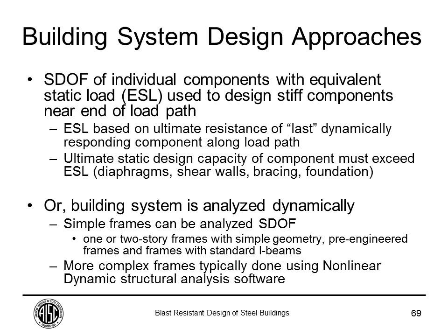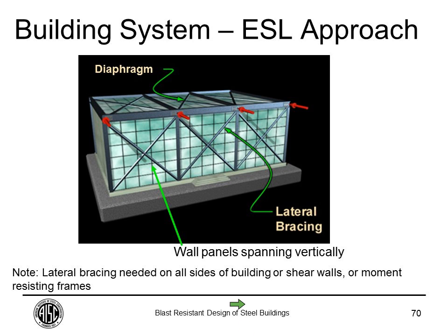The different approaches for frame analysis: the first one, which is the more simplistic one, is when you take the equivalent static loads from your facade elements and you apply them as lateral loads on your building. Or you could do a single degree of freedom representation of your frame. You may use simple equations that are available from structural dynamics books to determine the single degree of freedom parameters of your frames, or you can use structural software to do pushover analysis and determine that resistance function. So for example, in the first approach, if this was our building, we know the facade is spanning floor to floor. We can calculate the equivalent static loads, which are the red arrows, and apply them laterally, and then just use a typical static lateral analysis to determine our bracings and our foundation loads.